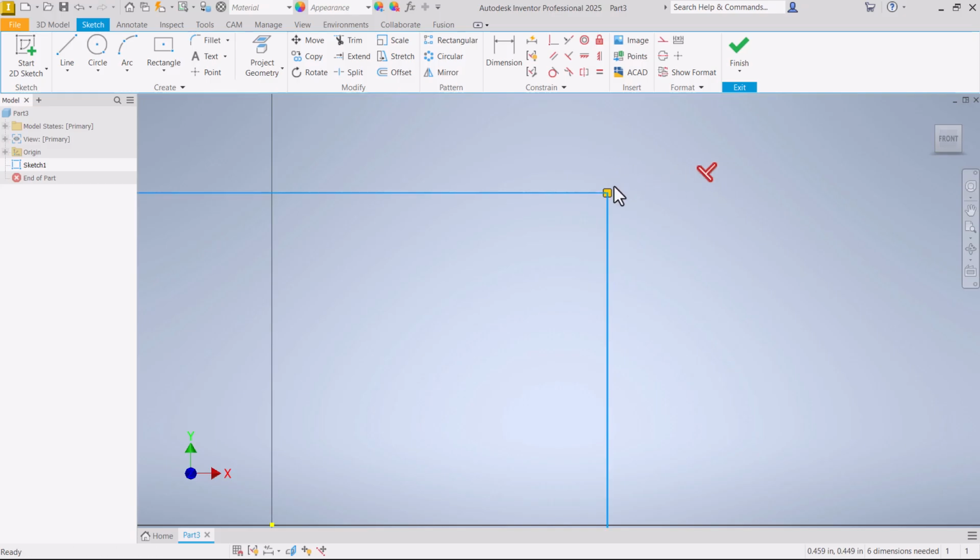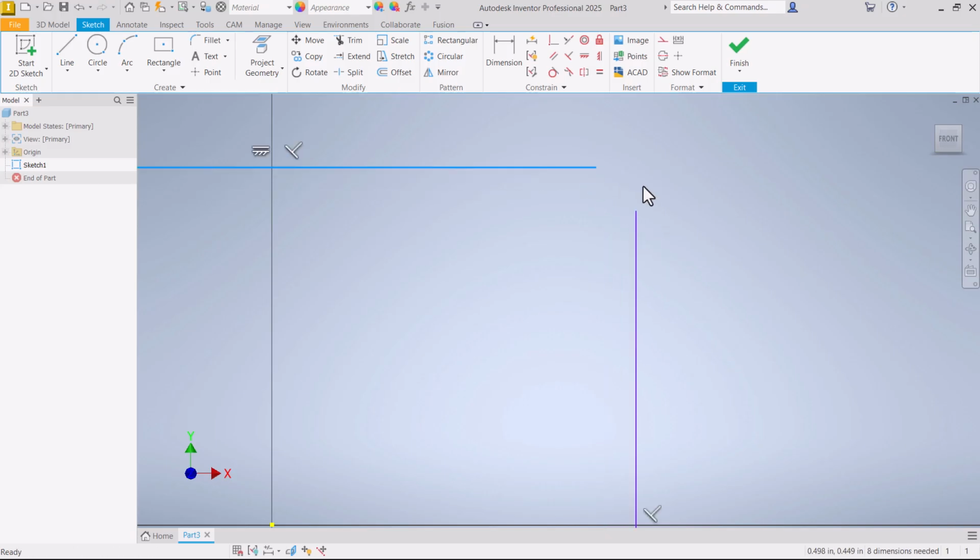Let's move that aside, move the mouse cursor over that little yellow dot, and we get these two coincident constraint glyphs or symbols that pop up around the endpoint of that line. Notice there are two of them here because I have one for each line. Each line has an endpoint. They are constrained here together. So that means I have both of them. If I delete one, that deletes that pair. They always come in pairs.